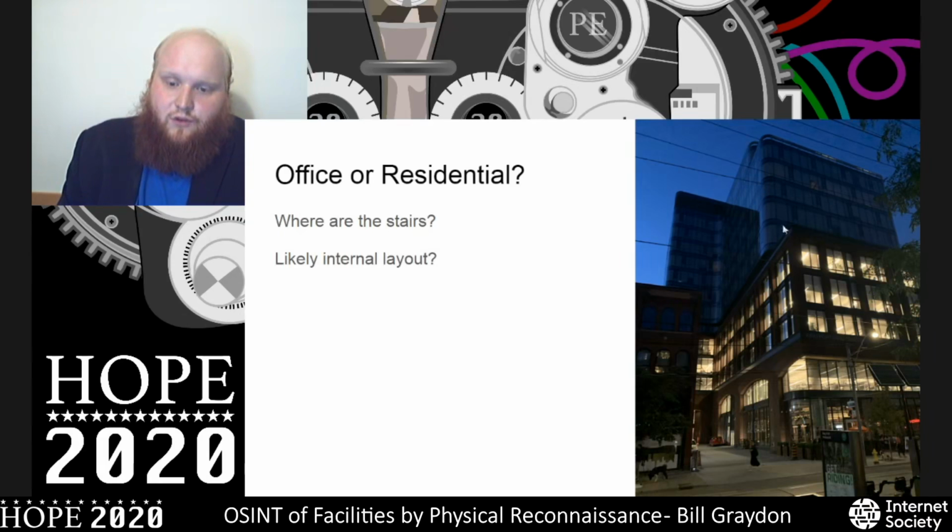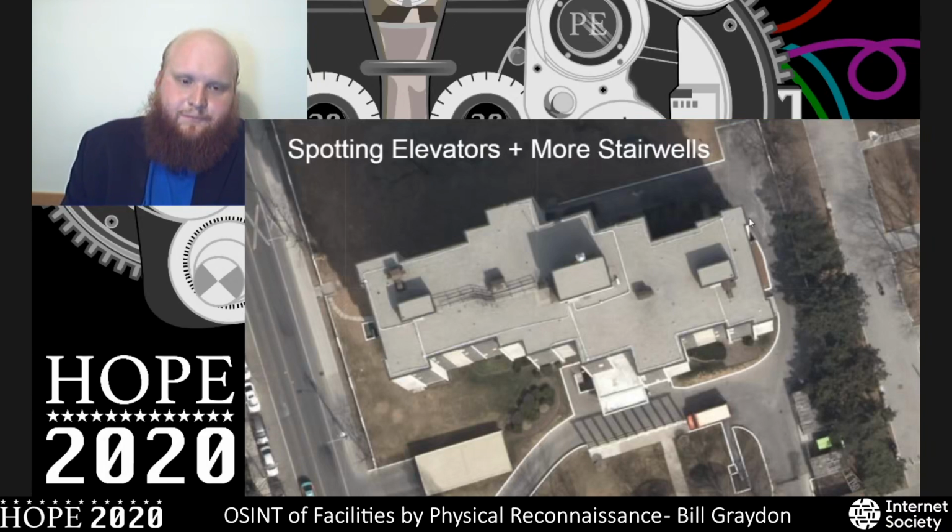It's clearly a newer construction that was built incorporating an older facade or older structure. And so because of that, there might be staircases on the outside of the older structure, but we don't see any lit columns of windows in this newer structure. Because of the fire code, there has to be emergency lighting there, so we can infer that they are on the inside, and this being an office building, it's likely an open layout that might be partitioned by the tenants.